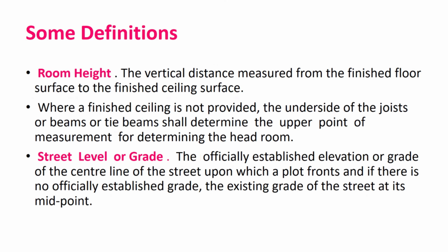Now they have another type of structures, linear structures, say roads or railways or embankment or the pipelines, maybe boundary walls, tunnels, retaining walls, transmission lines, etc. So they have given certain other requirements. Boreholes at spacing of 50 meters to 500 meters. In highly erratic substrata, spacing may be suitably reduced, in uniform substrata may be suitably increased.